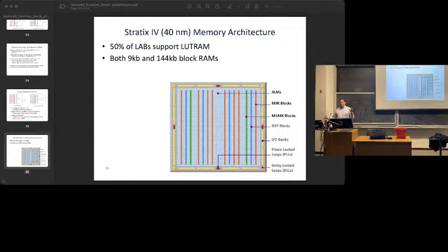So maybe there are a few people who might turn 75% into RAM, but not that many. Because it's costing about 15% more area to add that write circuitry in, if you're pretty sure not many people are going to use more than half their logic that way, then just putting it in half the logic blocks amortizes the cost. So that's what they did. It does mean they have to lay out 2 different versions of the logic block. So you have some columns with write circuitry and some columns without. So it does actually make the FPGA a little harder to design, but it does save some area.